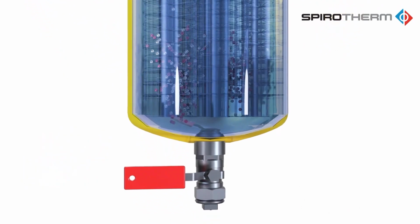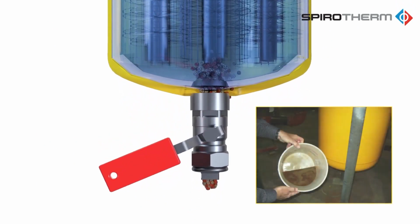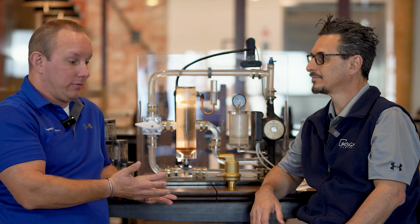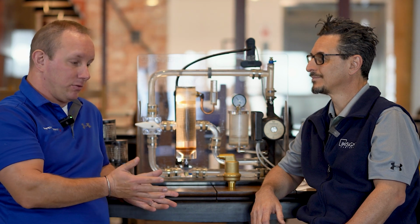One more question about the air. How does air get into a sealed system, typically? Does it come in through the makeup water? Let's say a chill water loop that's not open like a cooling tower. There are quite a few ways for air to get into the system. One of them is maintenance. Whenever you're doing maintenance, you obviously open the system, so a lot of air naturally goes in there. Makeup water actually has roughly 10% dissolved air.